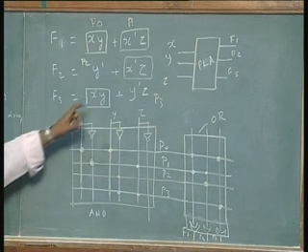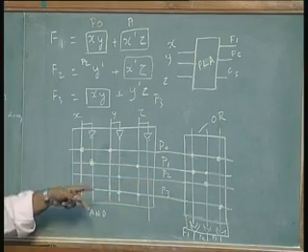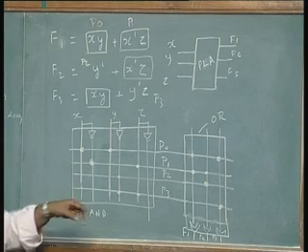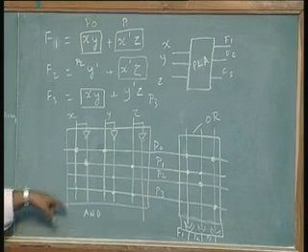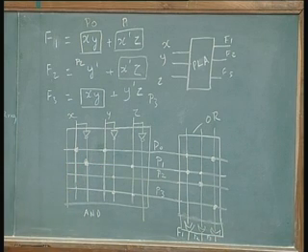And the fact that we have simplified such that common terms are available between different F1, F2, F3 functions, I can reduce the number of product terms I need to generate. That is the trick in programmable array logic design, programmable logic array design. You simplify such that as few product terms are possible totally, not for individual functions. That is the only thing.